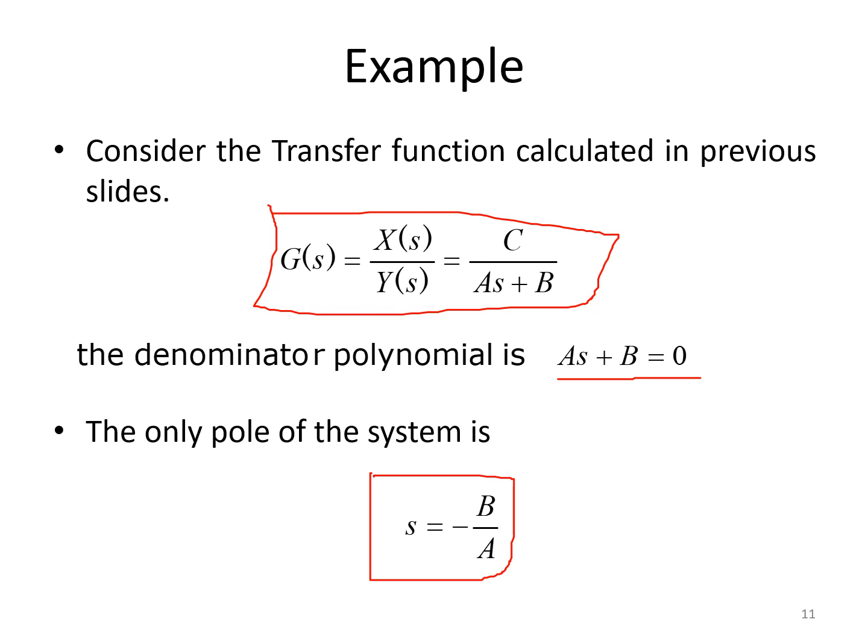Similarly, by equating the numerator polynomial to 0, I'll get the location of my zeros. Here, since I've taken only one constant, there are no zeros. And here, as you can see, we have one pole. The order of the system is equal to 1. This is a first order system. Similarly, the power of s in the denominator polynomial gives you the order of the system, or in other words, the number of poles in a transfer function gives you the order of the system.